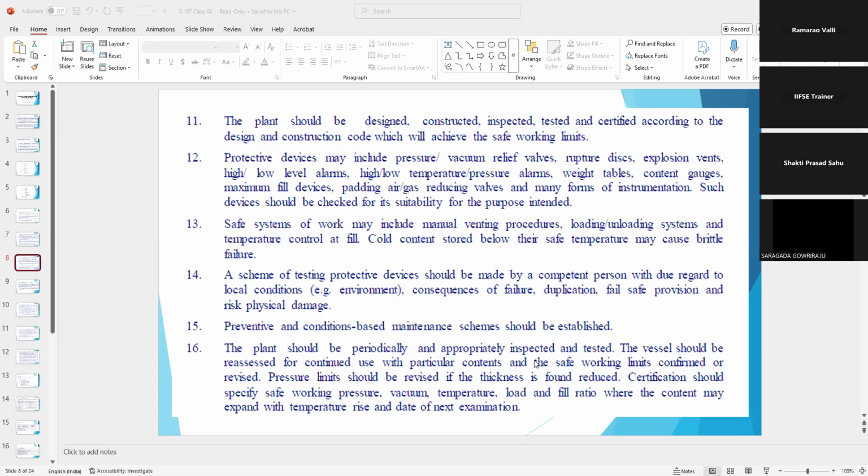Air receivers we do commonly, right? Because with air receivers, when you have a compressed air system, the receiver tanks will have, due to the moisture content in the air, water settling at the bottom. So there we do manual venting on a day-to-day basis. If your system is sophisticated, it may depend, but otherwise you do manual venting for these air receivers.